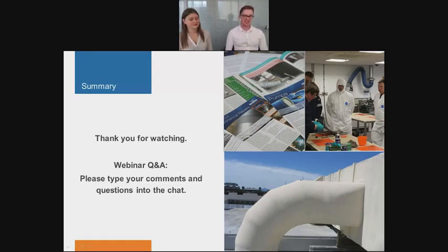So yeah, it's a good engineering solution for where maybe you can't access the other side of the tubes to push the compressed air through, or maybe the tubes are so long, or it's one of the systems where it loops back on itself, and you can't force enough air through to get the corks out. So yeah, it's a very good solution to a fairly simple problem, I guess. And it saves time. It does, yeah. Saves a lot of time, yeah.